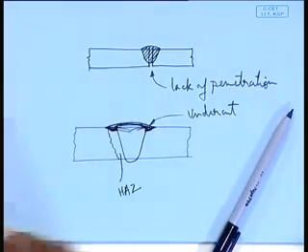And since it's related to speed, whenever there is a case of undercut, it continues for a certain length before the welder observes that this is happening. Only then you stop the weld process, check the parameters and redo it. So, that is what is undercut.